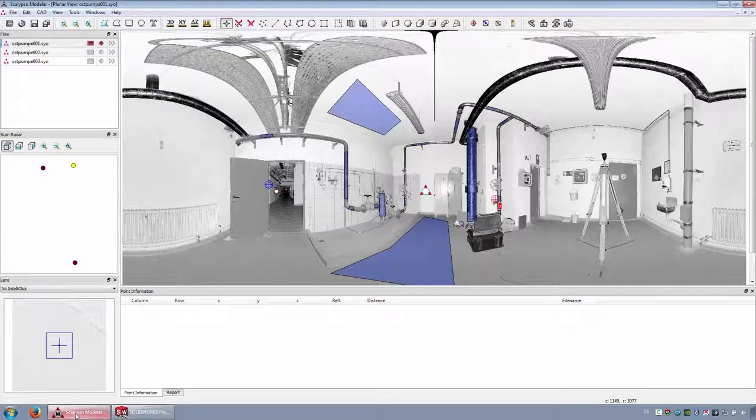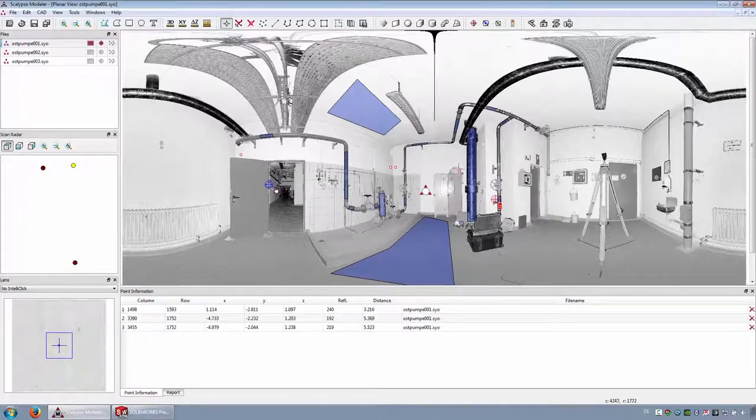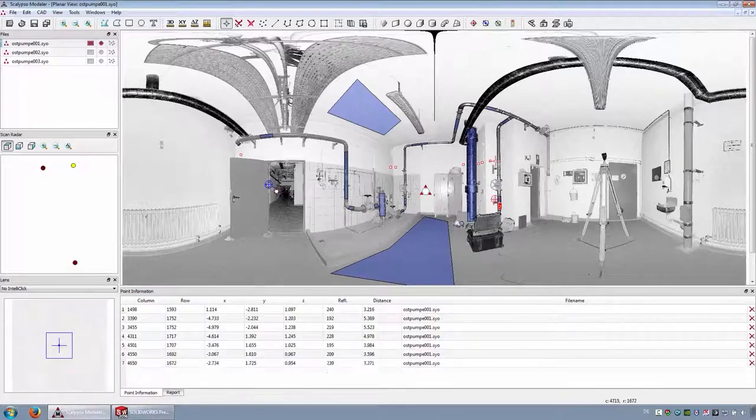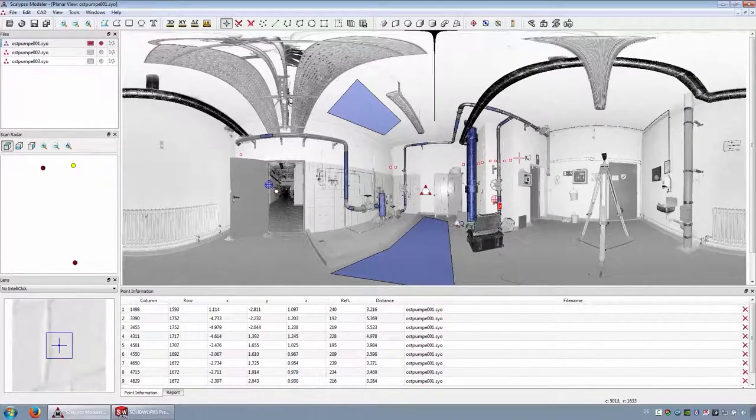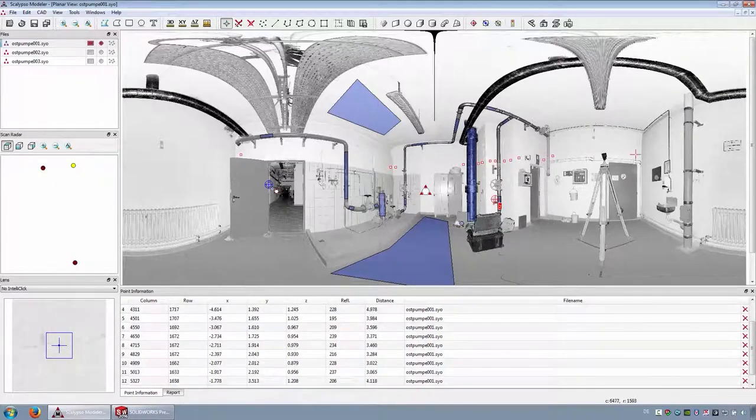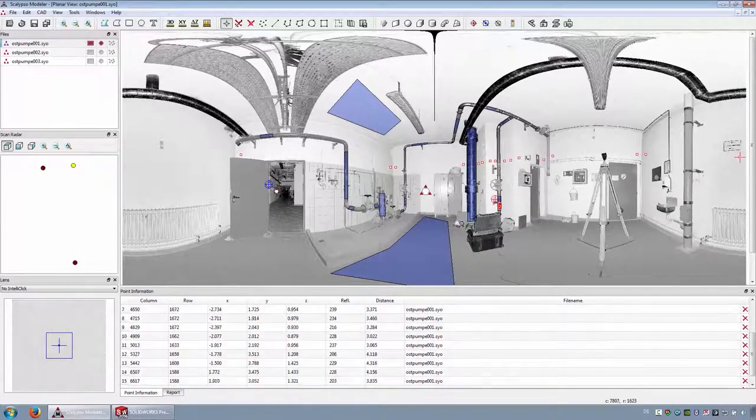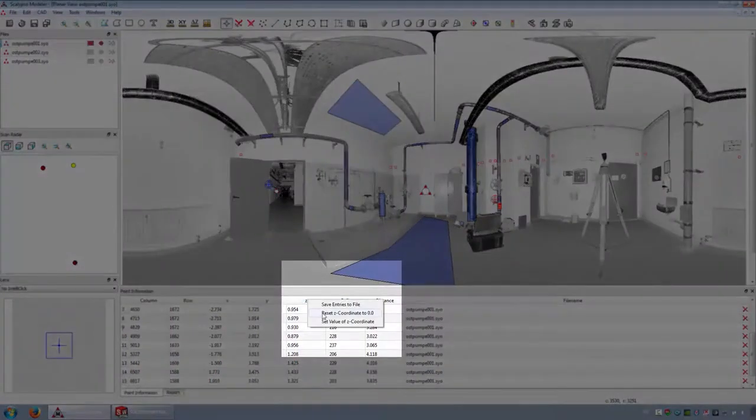In the next step, the room boundary should be transferred. For this, the function Export Intersection of the line segments is available. For that purpose, 2 points per wall must be sequentially selected. In the point list, the height of all points must be set to the same value.